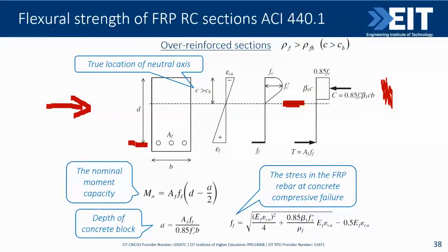Another problem is the well-known flexural resistance factor of 0.9 for structural engineers, which is used for ductile failure of steel reinforced concrete. In this case, it cannot be used at all, so the resistance factor is lowered to 0.65. Now, all standards technically allow over- or under-reinforced design for this.